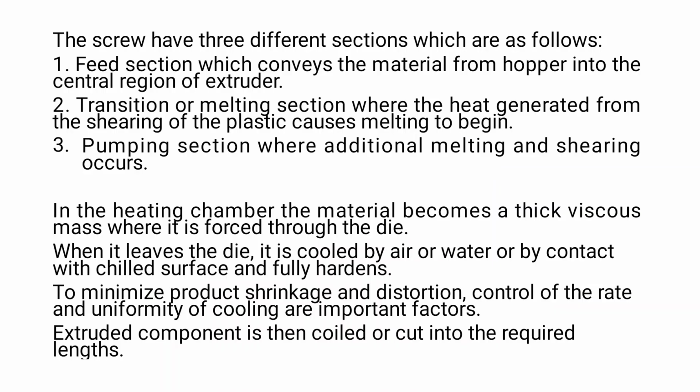The screw has three different sections: the feed section, which conveys the material from the hopper into the central region of the extruder; the transition or melting section, where the heat generated from the shearing of the plastic causes melting; and the pumping section, where additional melting and shearing occurs.